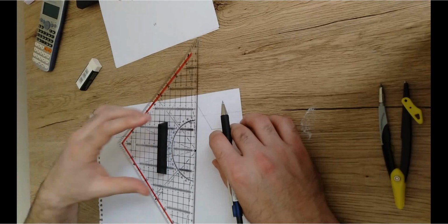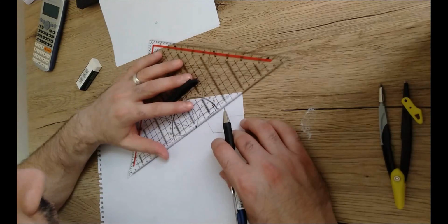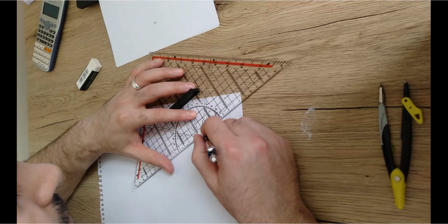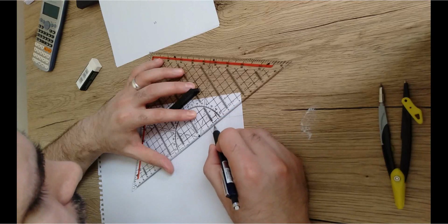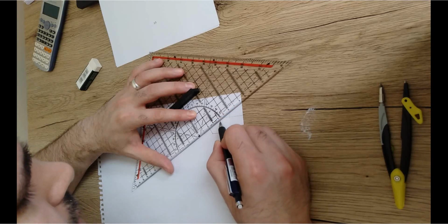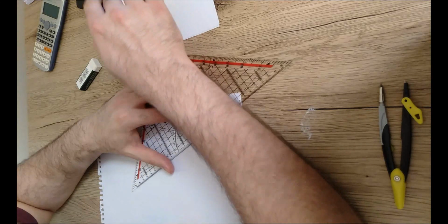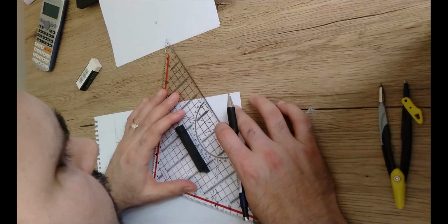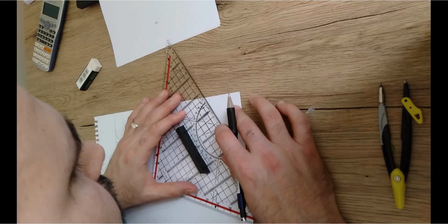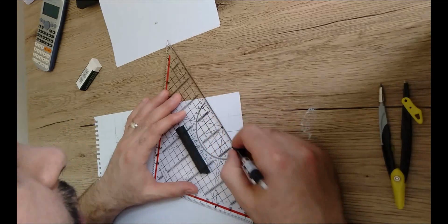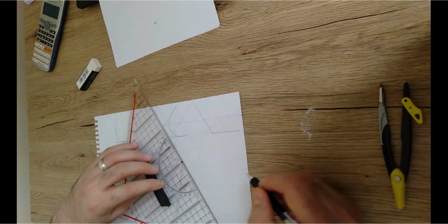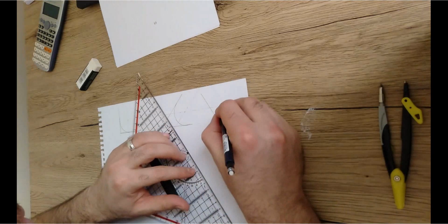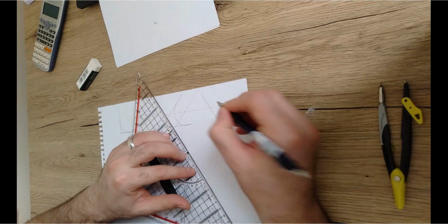Then we have to do the same. So we have to measure from any point, draw a very light line that is perpendicular to this line. Then measure over this very light line 10 millimeter and 10 millimeter, 20 millimeter, and mark a point. Why 20? Because the radius of the curve is already 20. Then from this point, you're gonna draw a line that is completely parallel to the baseline or the original line. And this is the benefit of the set square in this case, that you can easily find these parallel lines simply. Then the intersection of these two lines is going to give us the center point.